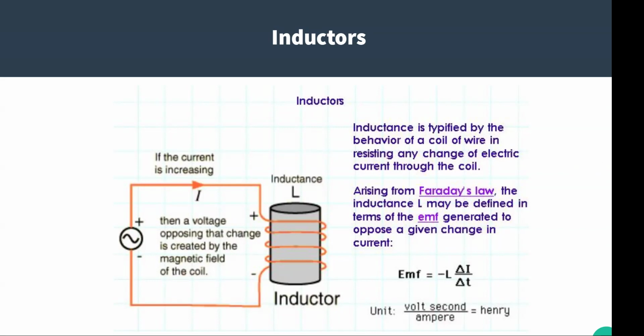That's due to Faraday's law, where it has what we call a back EMF, which is equivalent to the amount of inductance and the rate of change of the current. So the faster the current tries to change, the higher the opposing magnetic field is. It's much more important when you get into motors and things, but it's also in transformers.